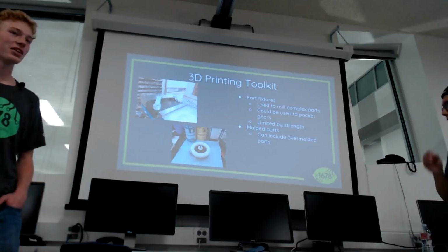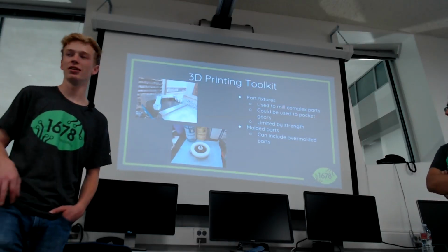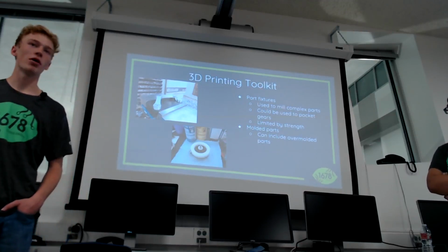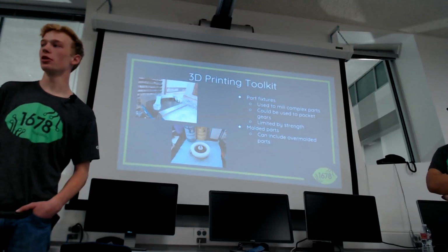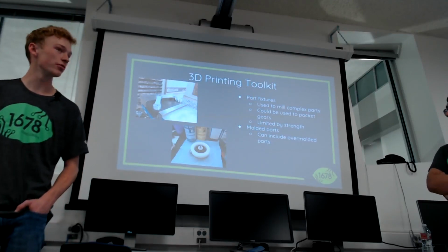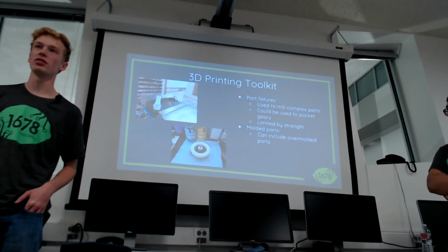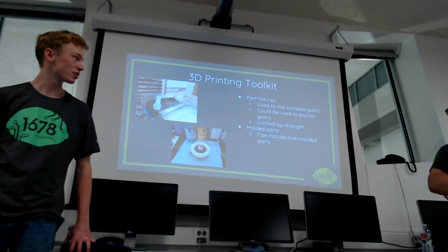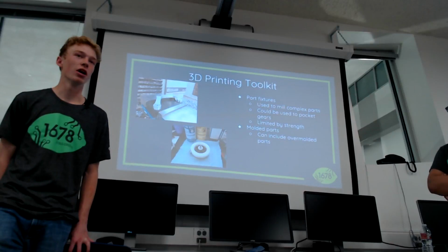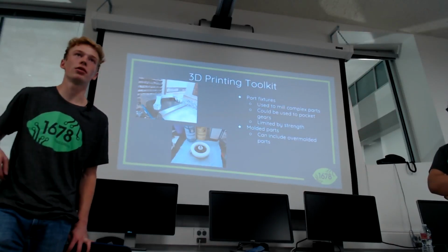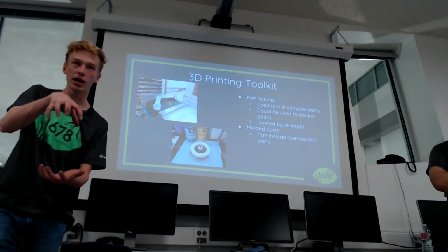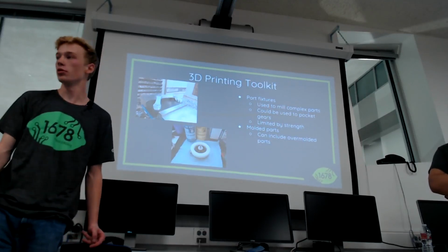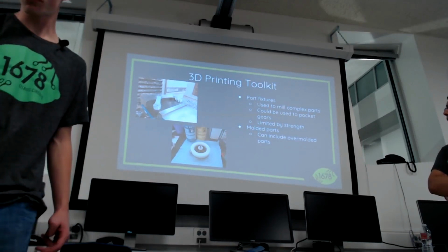One thing I wanted to add is just kind of a possibility. Disclaimer, I haven't actually tried this, but it would technically be possible. So if you wanted to pocket some large 20 DP gears on your robot to save a little bit of weight, normally it's not an easy thing to do because you can't just clamp a gear into a mill and expect to machine it out. But it would be possible to make a 3D printed fixture so that you could slide the gear into it and then pocket out the gear. So it would be kind of cool to do.